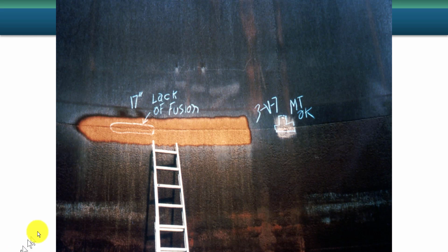Here's an example of corrosion in the groove welds, and it's a little bit rare or unusual, but the chemistry shouldn't be different enough that you get preferential corrosion here, but obviously in this case you do. Unfortunately, many people don't bother to do the forensic analysis. It would tell them why this is happening, so not too much is known about this groove-like corrosion that occurs at welds. Now, a horizontal groove is not hazardous because there's no axial stresses. If the groove weld was occurring in the vertical weld, that would be a dangerous situation, and that does occur. Another shot of the corrosion which seems to be attacking the weld itself.